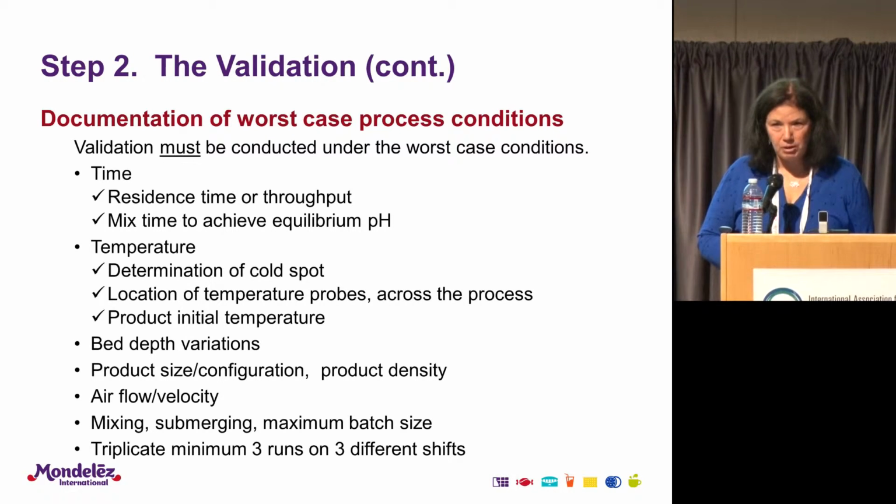Airflow and velocity, make sure all the fans are moving, possibly do your validation with one of the fans off to present a worst case condition. And if you do mixing or submerging, make sure that your batch size is conducive to being submerged totally in your tank. Okay.